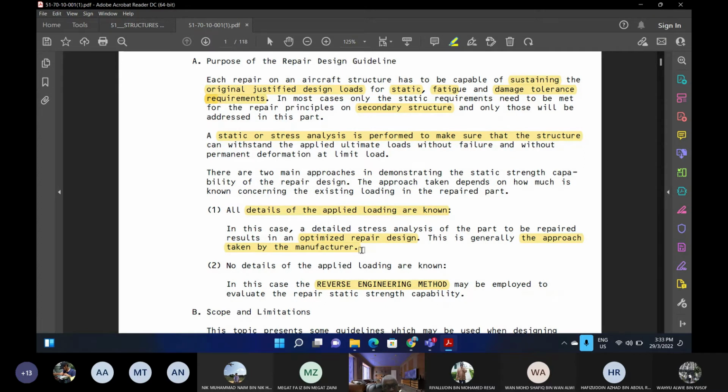When I was working on the C130 for Airod, we did have this stress manual, and it was easier for us, because every time the aircraft was damaged, we just went to the manual and referred to the part that had been damaged. We knew exactly what the part is used for, what kind of load goes into it, how much tension, how much shear, how much bending, torsion, and also in detail the factor of safety for that component, for each part. So it was easier for us.